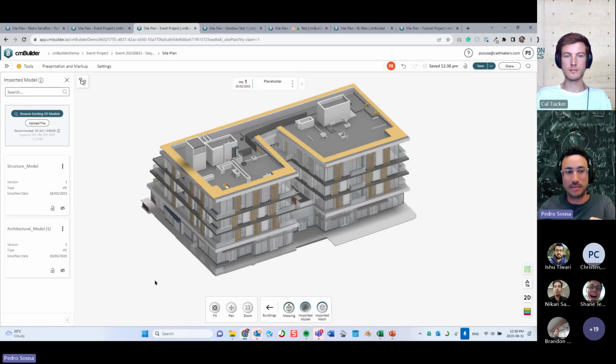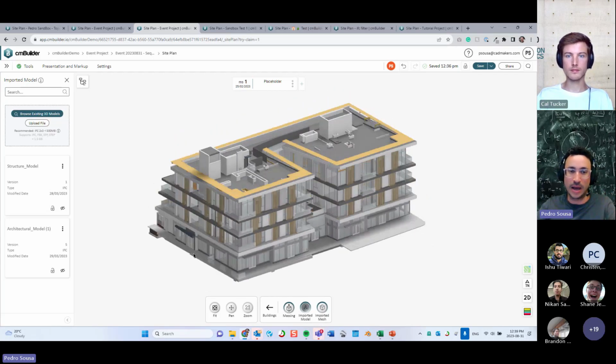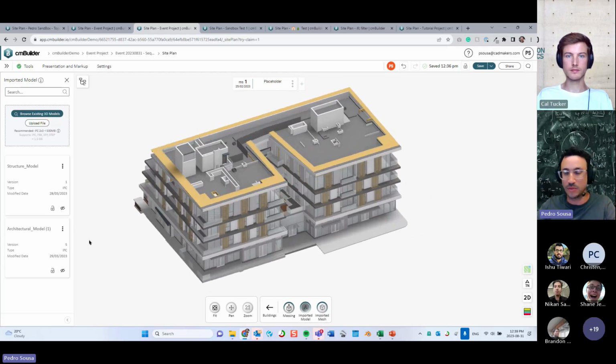If you bring back that model, it will show in the same position and you won't lose any of the work that you have done, right? So you are just removing it temporarily, so your tree structure will focus only on the parts that you want. And then when you bring it back, the position of that model will be in the right location. Cool. So I just wanted to give you guys a little bit of